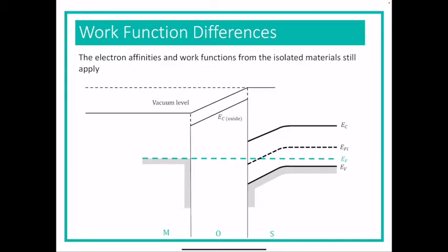So the value of the work functions in the oxide, the chi value for the oxide, the work function of the metal, and the chi value for the semiconductor material, the work function for the bulk material, and then the band gap between the conduction energy and the Fermi intrinsic energy is going to be about half the actual whole band gap.